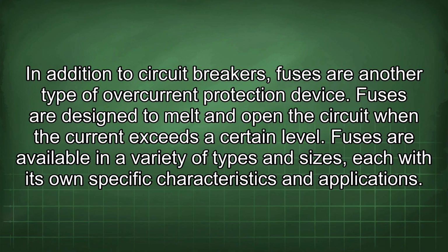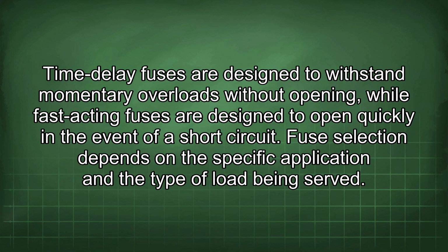In addition to circuit breakers, fuses are another type of overcurrent protection device. Fuses are designed to melt and open the circuit when the current exceeds a certain level. Fuses are available in a variety of types and sizes, each with its own specific characteristics and applications. Time delay fuses are designed to withstand momentary overloads without opening, while fast-acting fuses are designed to open quickly in the event of a short circuit. Fuse selection depends on the specific application and the type of load being served.